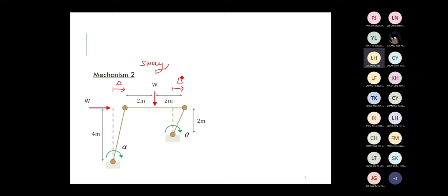And based on this picture, you can see that if one side is under rotation alpha, the rotation on the other side should have different values if they have the same displacement. Here, I just arbitrarily assume that one is alpha, one is beta. They are not equal. So if you set up the energy equation, then you will see alpha, beta in the same equation. You can't solve it, right? If the equation has more than one rotation angle.